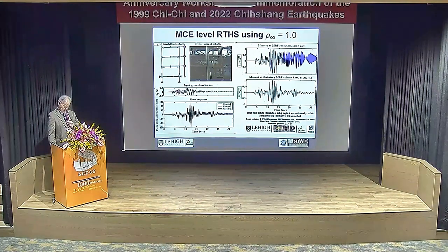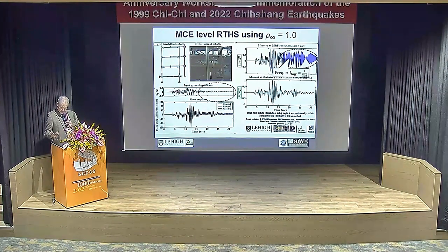And if you look, this is the acceleration, the ground motion. We're only looking in one dimension here. You say, wow, the earthquake subsided. What's happening here? This is the normalized moment in the RBS. It's ringing. This is the analytical substructure. You say, is that real? It's not real. What happens here is, when you study it, it's got a frequency of 1/2 delta t.